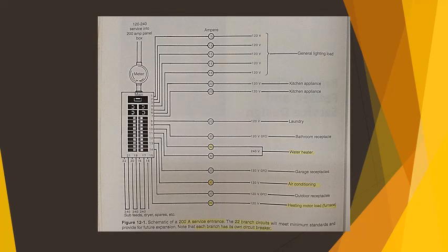Designing a safe and efficient electrical system is a responsibility that an electrician cannot take lightly. The system must be large enough to handle the loads that will be placed on it when the home is new, as well as when it's 20 years from installation. To ensure a quality electrical system, you must calculate the loads, determine the safe number of circuits to install, and select the proper conductors and equipment.